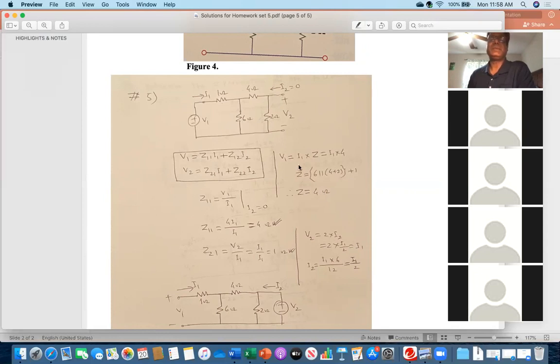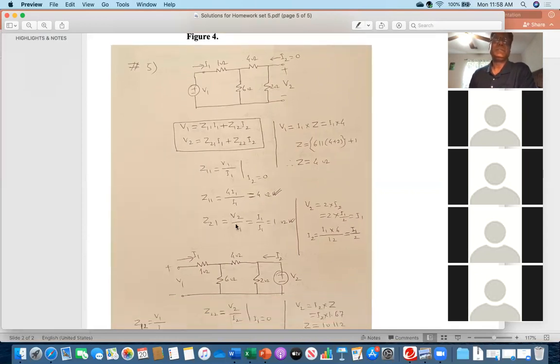So therefore, I have written the V1 equation, Io multiplied by 4. Now come back to the G11 expression, that 4 into Io is the V1 value. And Io as it is, Io cancels. 4 ohm. This is one answer. Now you need G21.